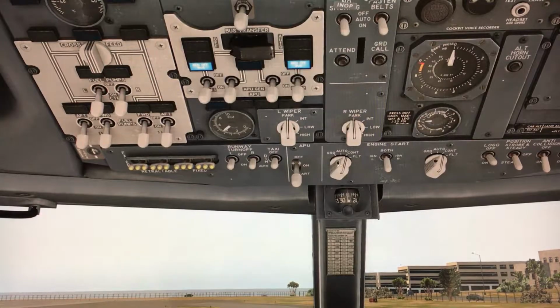when we're flying, we switch to this slot. So when one engine stalled or lost power, we can use another engine to cross start. See, the left engine has failed and you need to restart, but your APU is not running when you're flying in the middle of the air. What else can feed the air and turn the power to the left engine? Your right engine. This is basically what we do for both engines, just in case engine 1 stalls in the middle of the air without the APU running at the same time.